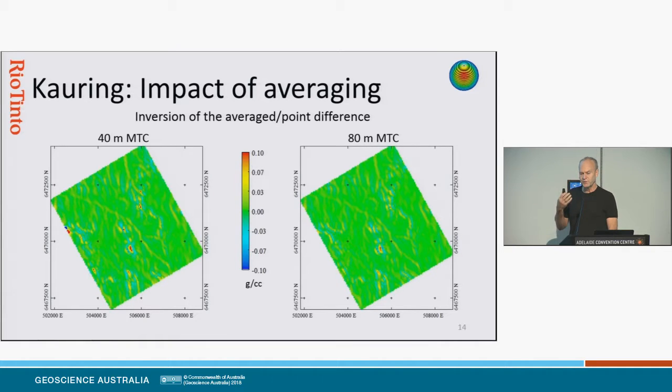Because obviously when you get data delivered, the major component is the terrain, and that's corrected for, and then you deal with the terrain corrected data in trying to interpret the geology. So in that process, if you apply a point correction to the terrain calculation as opposed to the measurements which are actually integrated, then you introduce an error, which is obviously one that we can deal with.